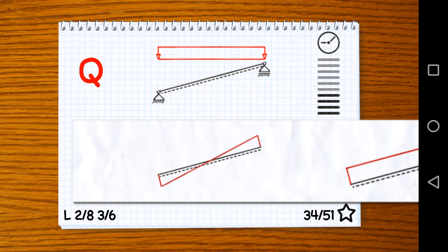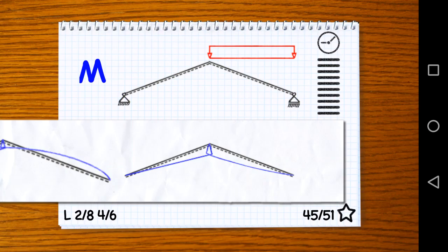Looking at the distribution, the shear force distribution from the right to the left will go downward, like the distributed force is also applied downward. Okay, moment equilibrium here at the pin support would lead to a vertical force at the roller support going upward.